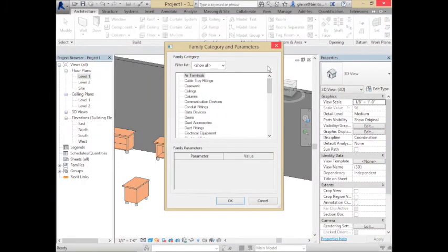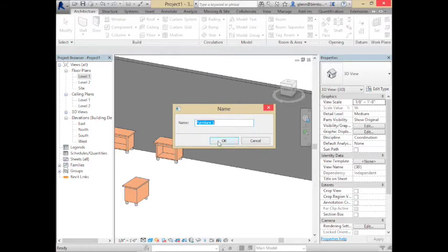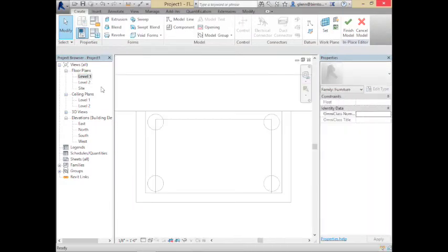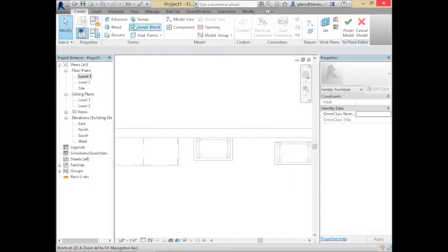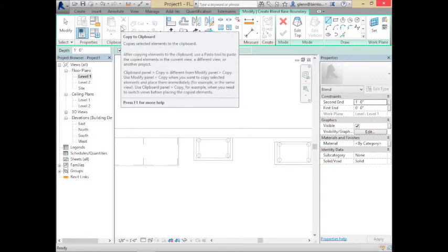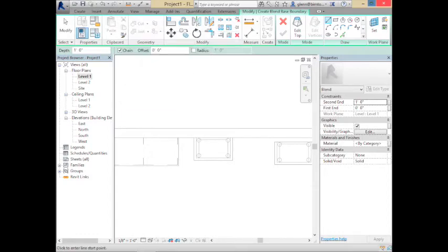But it looks something like this. I'm going to make another piece of furniture. This is going to be my twisty tower. So what's this one going to look like? I'm going to choose blend. When you choose the blend tool, we're going to draw a profile again. By default, what you draw is the profile at the base, the starting point. So I'll just draw some kind of rectangular-y thing.